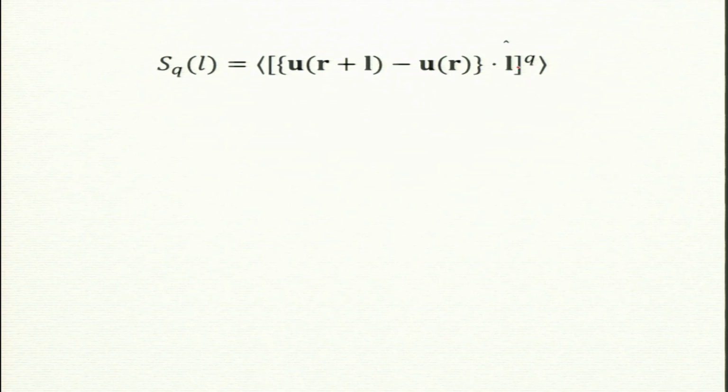So, we can take the projection along L again. L cap is along the L direction, or in fact it is n, the same as n. Take the qth order structure function, S_q, where q is the order. So, delta u to the power q, with q equal to 3, is what Kolmogorov showed. But if q is, let us say, 4 or 5, what happens? It turns out nobody has been able to get a closed form formula from first principles. Starting from the Navier-Stokes equation, we cannot get to q not equal to 3. For q equal to 4, nobody has been able to do it.